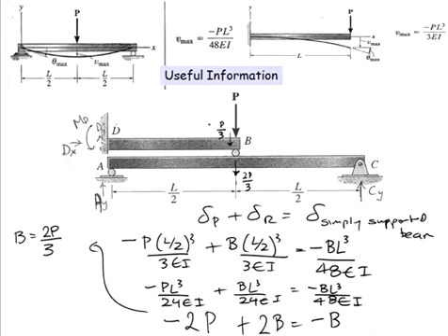And so if that force is P on 3, that reaction here must be P on 3. If the force coming down here was 2P on 3, you have a reaction here P on 3 and P on 3. So in effect, the simply supported beam is carrying 2/3 of the load, and the cantilever is carrying 1/3. And that's based on the lengths being the same and the EIs being the same. If this then had a stiffer EI, it would then attract more load.